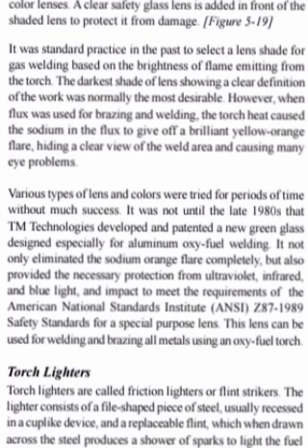It not only eliminated the sodium orange flare completely, but also provided the necessary protection from ultraviolet, infrared, and blue light and impact to meet the requirements of the American National Standards Institute Z87.1-1989 safety standards for a special purpose lens. This lens can be used for welding and brazing all metals using an oxyfuel torch.